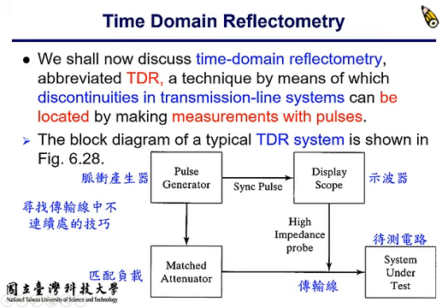the schematic of the TDR technique. So for the case shown, we have a system under test. It's the circuit to be diagnosed, which is made up of transmission lines. And you have a pulse generator. So similar to what we have in example 6.3, you have an impulse generator which provides impulse signals repeatedly. Pop, pop, pop, pop, pop. And here you have a display.